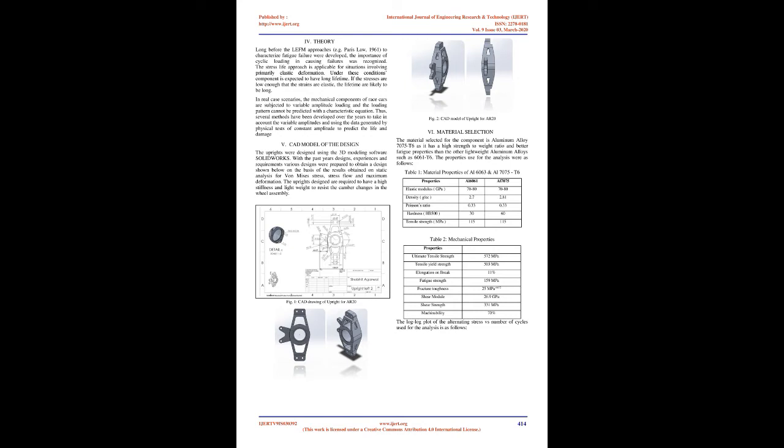The weight is the total weight supported by the two tires being analyzed. Acceleration is the gravitational force being experienced. In the case of front uprights, deceleration or centrifugal acceleration from turning. CG height is the height of the COG of the vehicle. Track width is the distance between the two tires being analyzed.